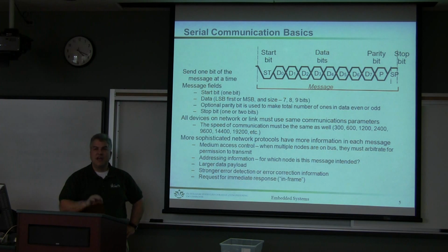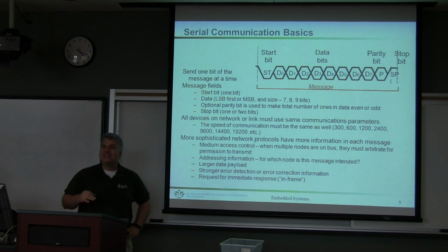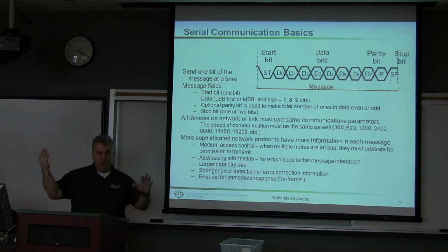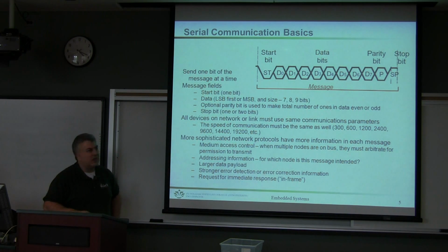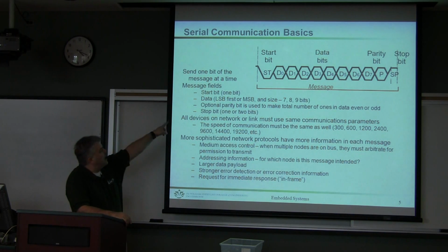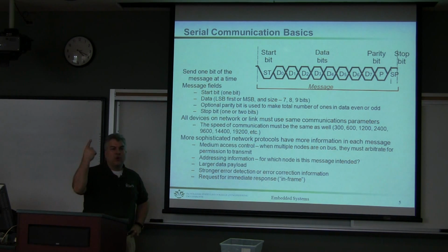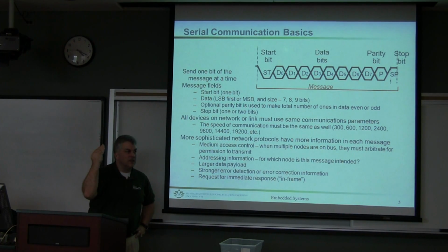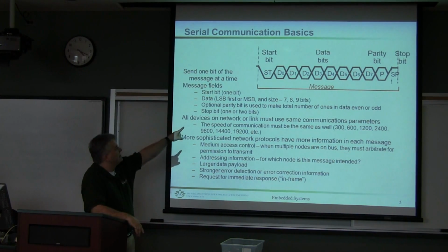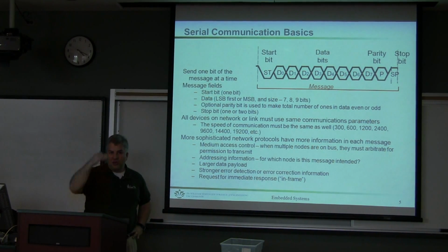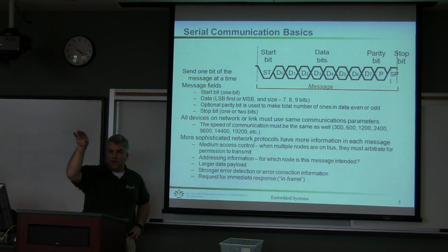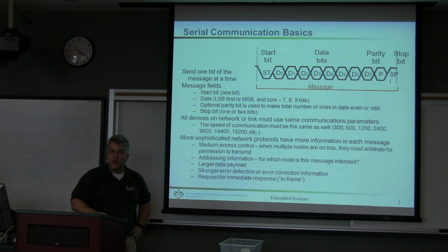So the reason you send asynchronously and set your expectations is that you have two different devices running at two different clocks. And how do you do that? Well, you have a start bit. When one machine is going to send something, it sends a start bit, which lowers its signal from a logic high to a logic low.